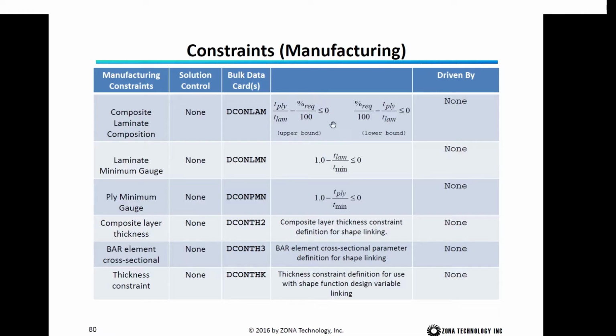because when we measure the property of a laminate by performing the coupon test, we cannot afford to do too many various thickness percentages. For example, we can only afford to do the coupon test of laminates which have a 0 degree ply from 40% to 60%.